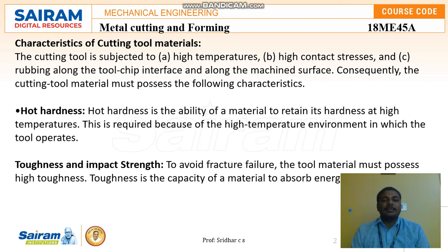High contact stresses means that more forces will be acting between the tool and the workpiece. In order to overcome the cutting forces acting on it, the tool has to withstand them. Cutting forces are created mainly by the high temperature, and the surface contact and friction are also some of the reasons that may cause high contact stresses. So high contact stress means the tool has to withstand more cutting forces.